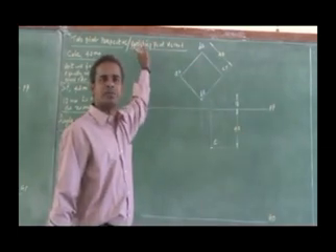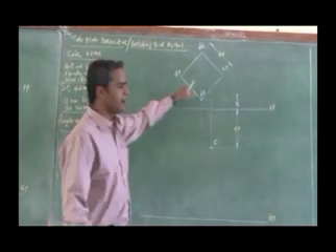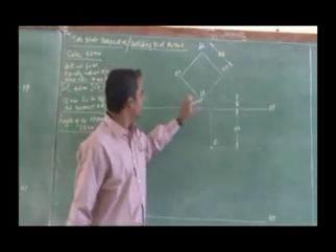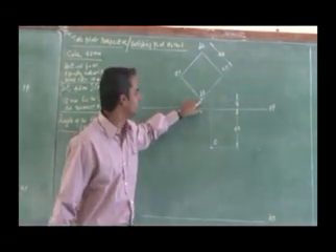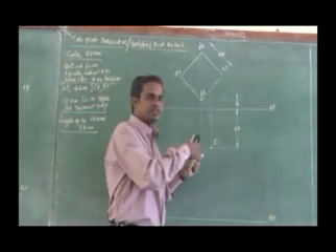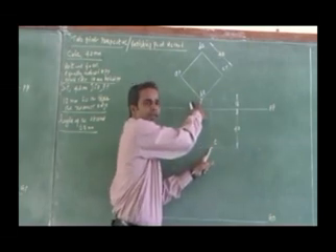If you are going for the vanishing point method or 2-point perspective, you see here, in the top view I have drawn, the faces are equally inclined and the edge nearest vertical. BQ is going to be my nearest vertical. Station point is here, observer is here. For him, the nearest vertical edge is my BQ.